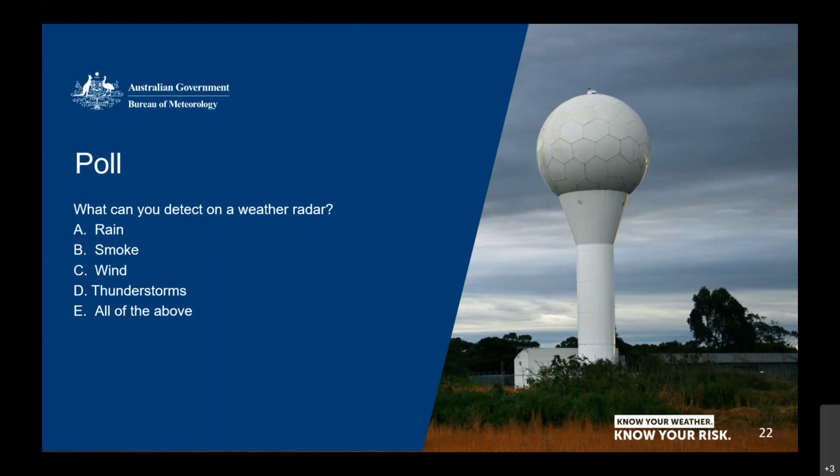Yes, I can answer that. The internals of the radar are very similar. The radars use the same sort of transmission technology, a magnetron or a klystron. The main difference is in the data processing and also the antenna. With weather radars, we use a pencil beam with a dish antenna. Air traffic control radars generally have a fan beam, very narrow in azimuth like ours, but in elevation they use a wider beam because they're looking for a solid metal target that could be anywhere. That's why they send out a wider beam in height.